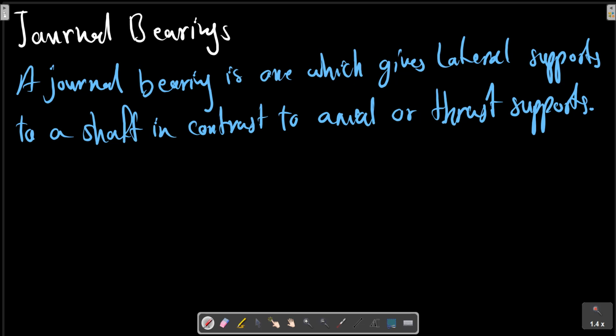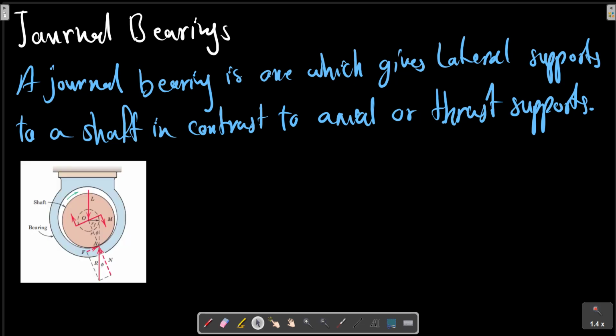For dry bearings and for many partially lubricated bearings, we may apply the principle of dry friction. The principle provides a satisfactory approximation for design purposes. A dry or partially lubricated journal bearing with contact or near contact between the shaft and the bearing is shown in this picture, where the clearance between the shaft and bearing is greatly exaggerated to clarify the action.